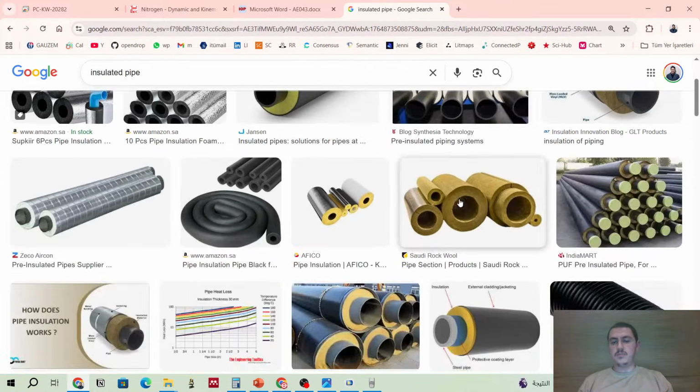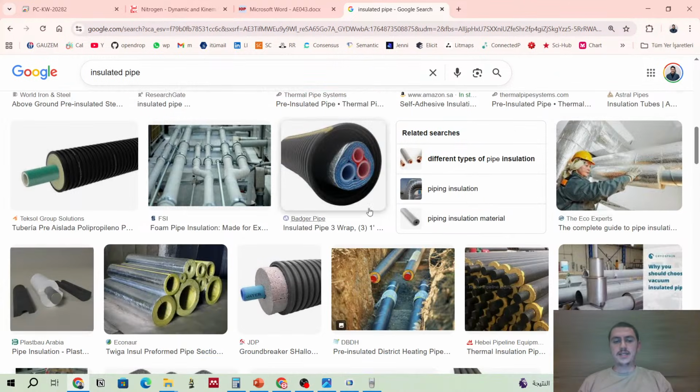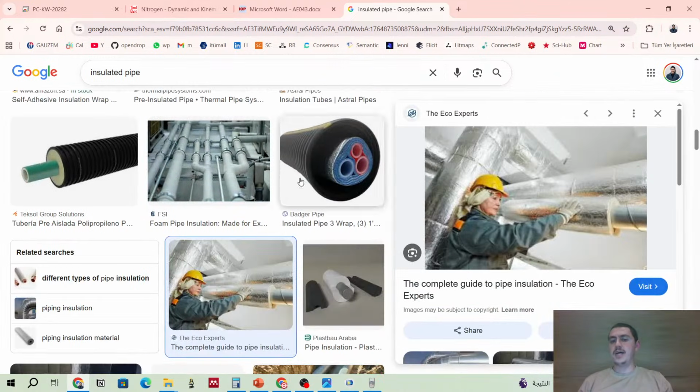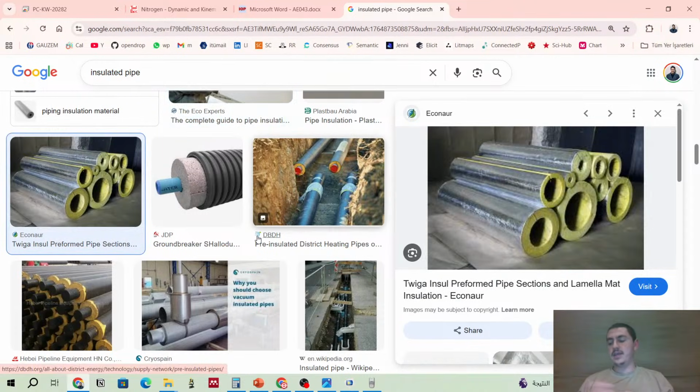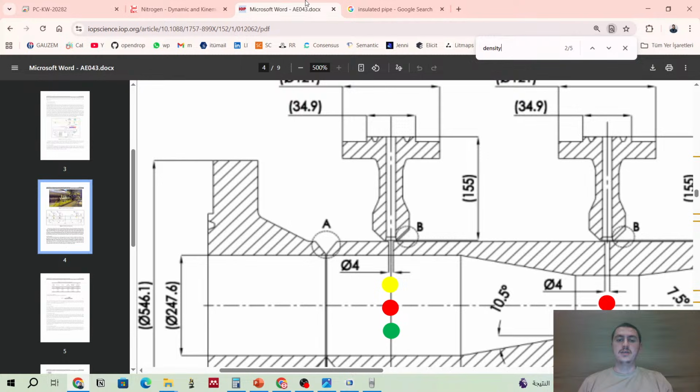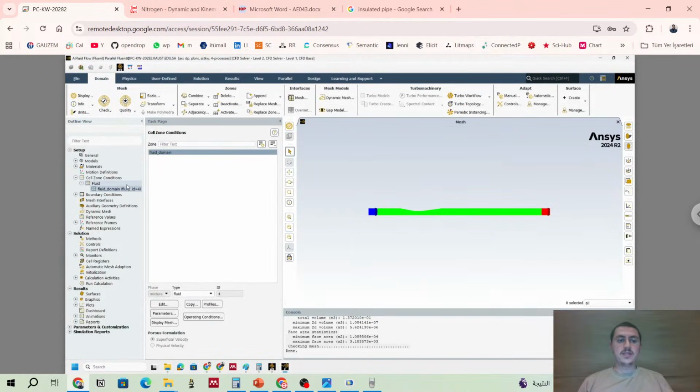It's very widely used in air conditioning pipes and ducts, because we are carrying a cold or extremely hot fluid, so we should insulate it. So it's heat transfer coupled with a fluid dynamics problem. Sometimes we also want another domain. We should draw this solid geometry and we will have another cell zone in our problem. We name it solid, and we select aluminium or copper or PVC, anything. In this problem we have only one domain, one fluid zone. So we defined it, we are done.